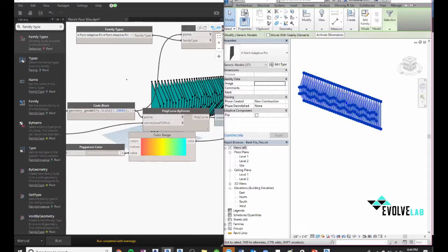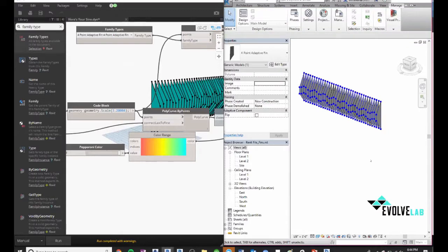So going through Dynamo to Fractal, picking your option, downloading the option, bring it into Revit. Keep in mind the differences between Dynamo Studio and Dynamo for Revit. You can start interacting with your components on the Revit side for Dynamo for Revit, and then you can actually start translating that geometry over into an actual Revit environment.